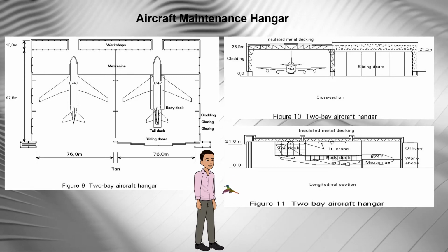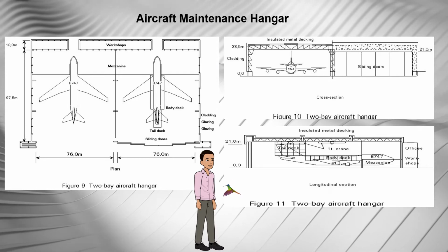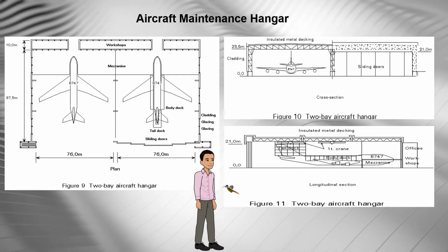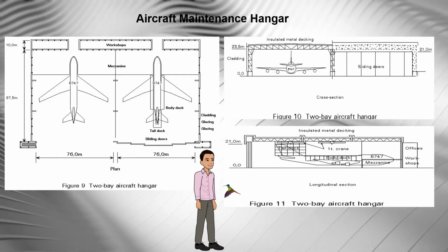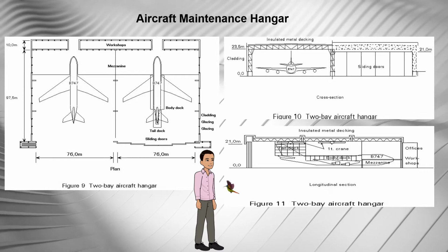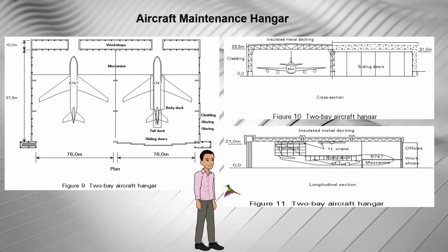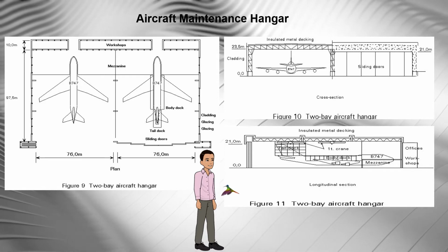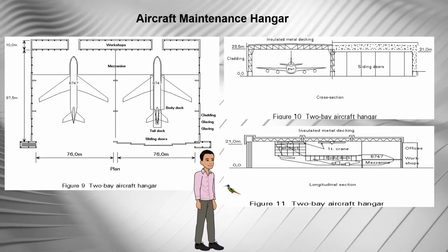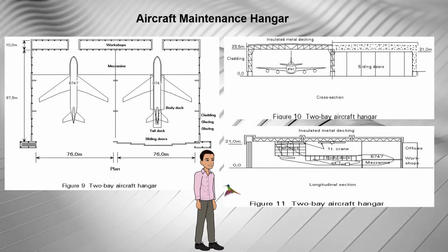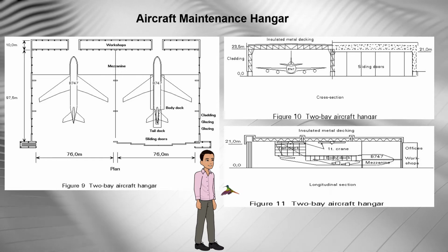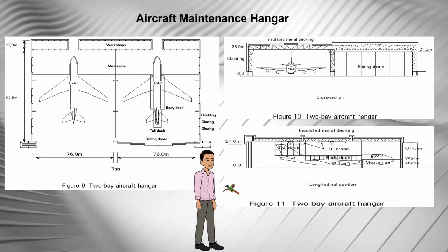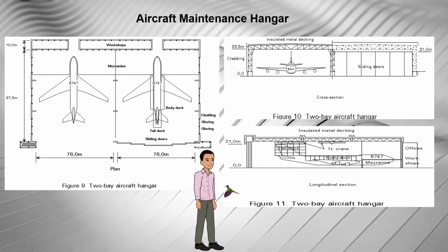This arrangement enables a large workforce to carry out maintenance. Typically, the docking consists of main wing docks, a tail dock, and body dock. They are moved into place after the aircraft has been placed in a fixed position. Since aircraft are jacked up 1.5 meters for landing gear overhaul, it is usually necessary for the docks to have vertical adjustment. The use of wheel pits can make jacking unnecessary, but this adds considerably to cost as well as adding to specialization.